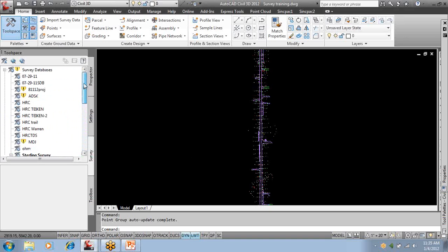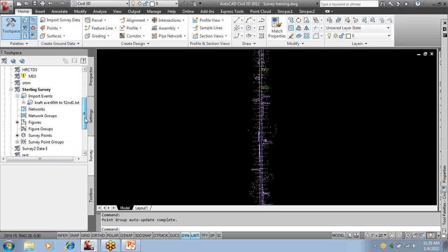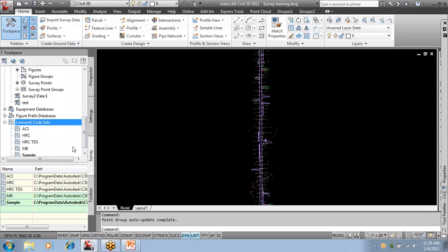So a couple of things on the survey side to get started. Check all of your settings. Make sure you're in the right units. Make sure you import everything through the survey data. And if you're doing line work coding, make sure you set up your line work code sets.